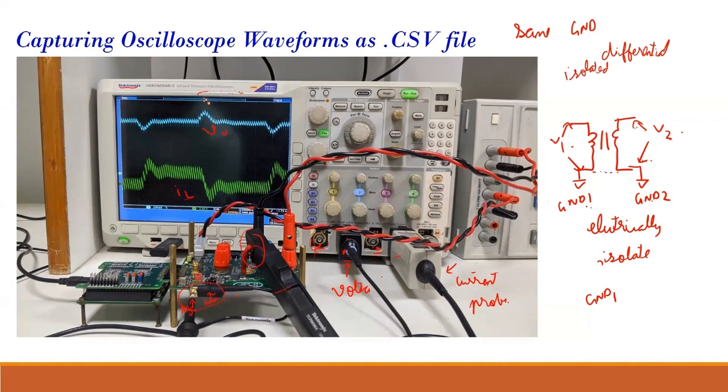Sir, in our multimeter we have one terminal to test for a short. Using that, if I touch both, can I say whether it is internally connected? Yes, you could do that.